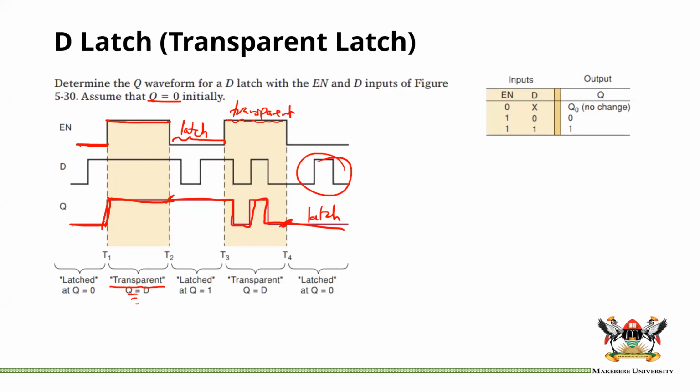So this is just a small difference from the D flip-flop, meaning that you can actually create a transparent latch, instead of a synchronous or clocked D flip-flop. You can say that enable is a control input, because as you can see, it is the one that makes your flip-flop either transparent or latched, or non-transparent, so to speak.